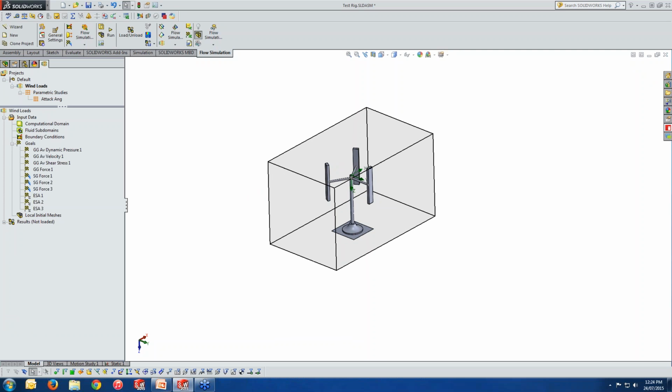This case is simply considered a wind tunnel, as we set up, with 12 meters per second in the X plus direction here. What is very important is that we are always trying to achieve an optimized simulation. In this regard, we have to make the software trace some parameters which are very important to calculate precisely, and also make the mesh resolution suitable.